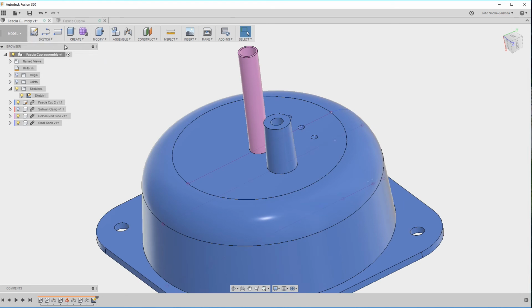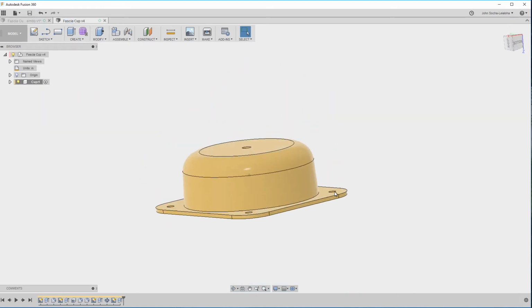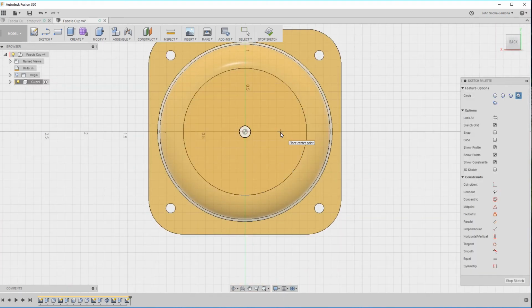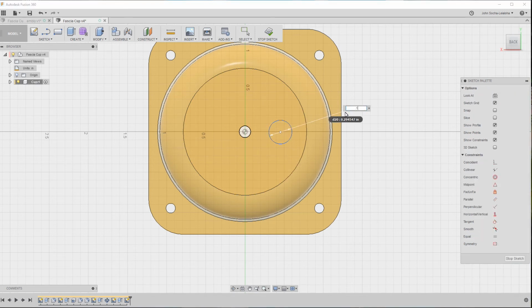So what I have here is this starts out at about radius of 0.135. So let's go ahead and add that. We'll figure out the distance in a second. So I'll add a circle to here. And dimension I said was 0.135 times 2. We want to make these two things horizontal, so I'll select them and say horizontal vertical constraint. They don't really need to, but I'm just choosing to make them horizontal.